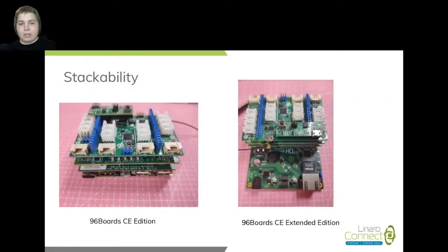Another benefit of using the 96Boards CE form factor is also the stackability. So, for example, you want to develop a product that requires a specific sensor and still want to have 4G LTE connectivity. You can have an LTE mezzanine and a sensor mezzanine stacked on top and develop with that.